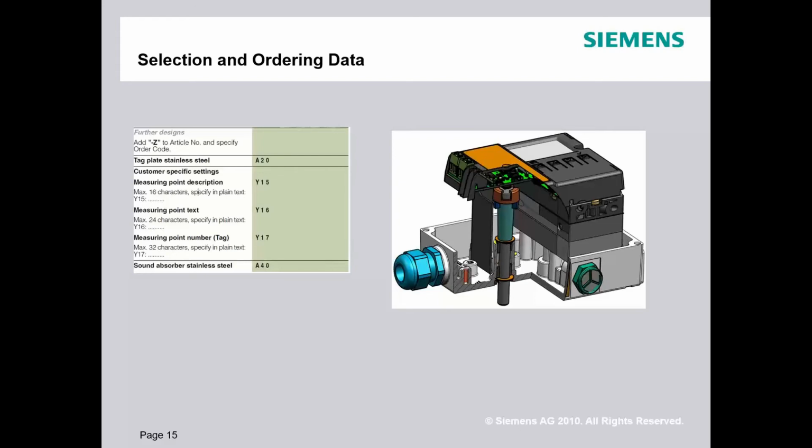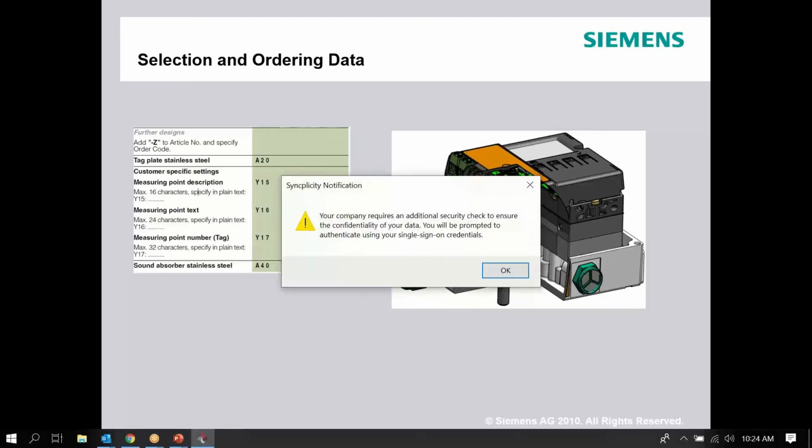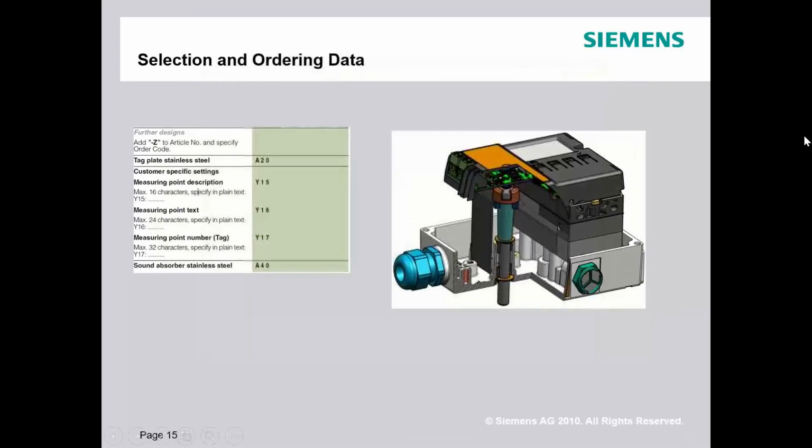So if you're in a very high vibration, I'm not talking about kind of shaking. I mean something like a high pressure drop letdown when you've got high frequency tuning fork vibration, and that valve's not moving very much. It's sitting in the same place. It's steady state. Eventually, that vibration will cause the wiper to kill a spot in the pot. If it kills the spot, now that positioner really doesn't know where to go. It starts to freak out. Well, that's why this was invented. There's no mechanical connection. It's all magnetic.